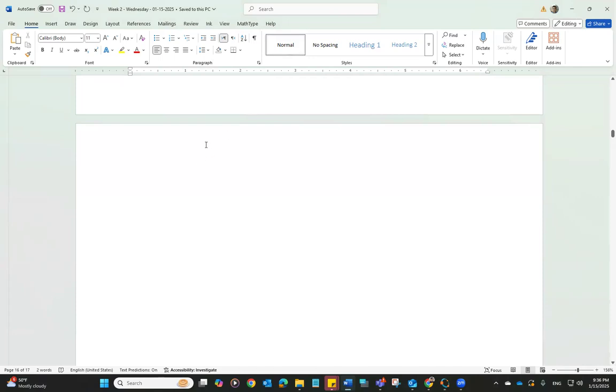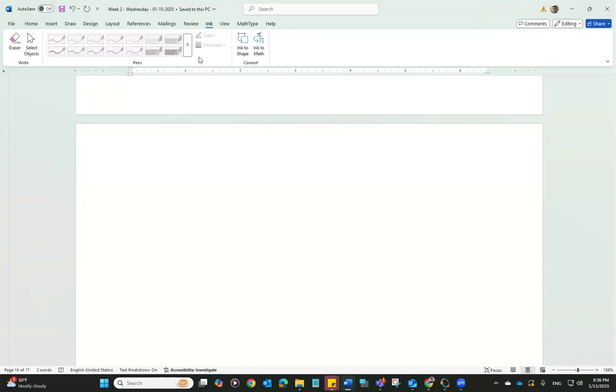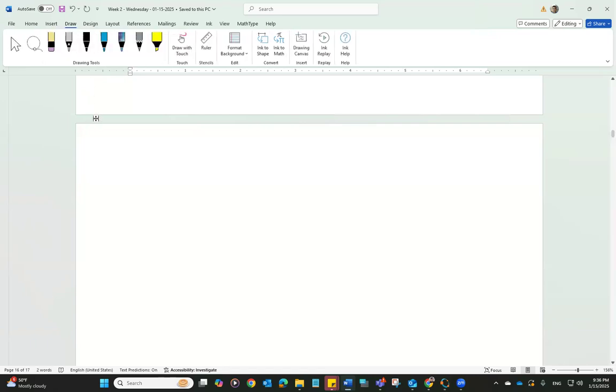You're going to choose one of the methods. Now, to calculate your open circuit voltage, that is still going to be done the same way as in the first method. That is, you're going to use circuit laws, whichever is the easiest way to implement on the given circuit, and you're going to calculate the open circuit voltage.